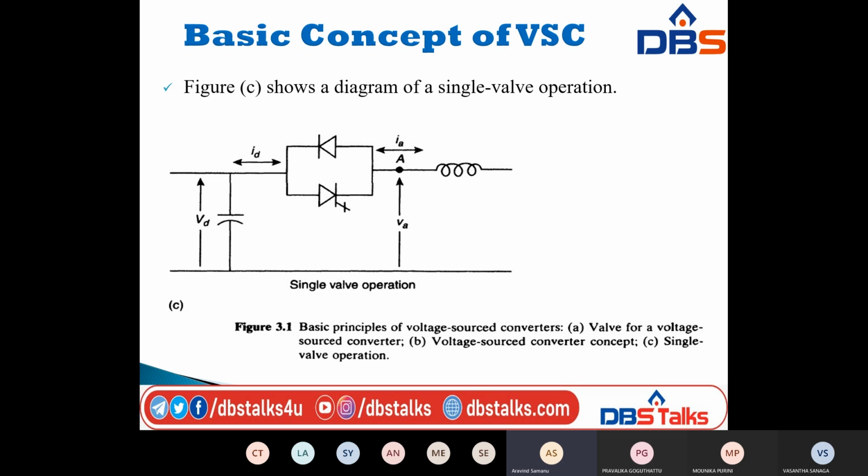So this is the turn-off device, a thyristor. This is the turn-off device. Here the positive polarity side is connected to the anode side of the turn-off device. That means when turn-off device 1, that is thyristor 1, is turned on, the positive DC terminal is connected to the AC terminal A. I indicated point A here, after connecting the converter valves.